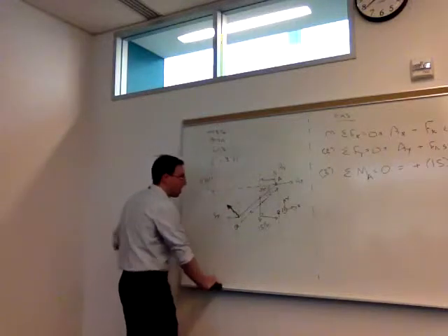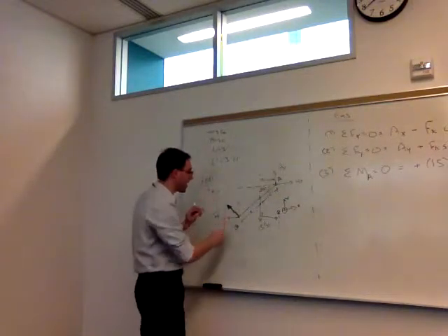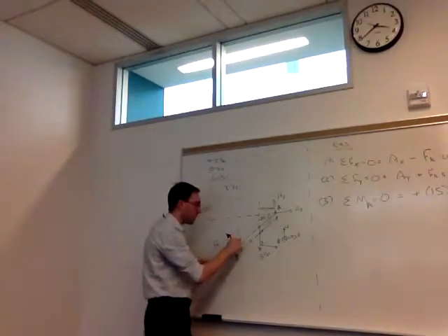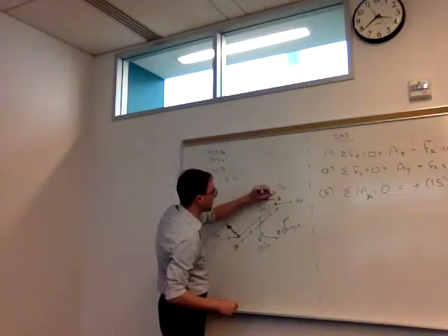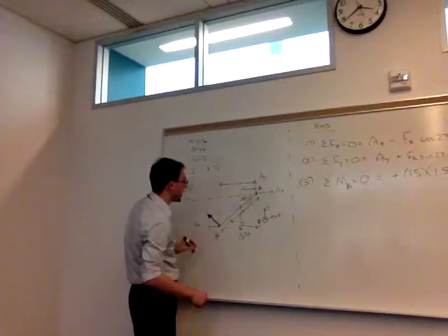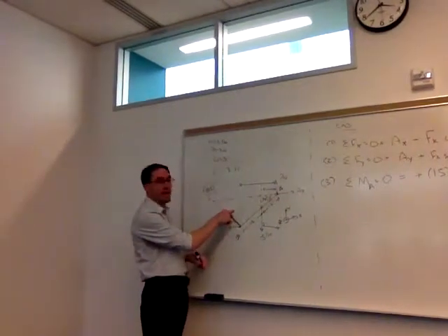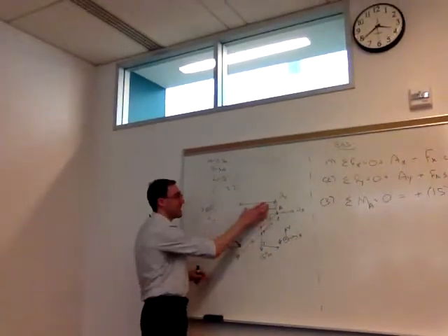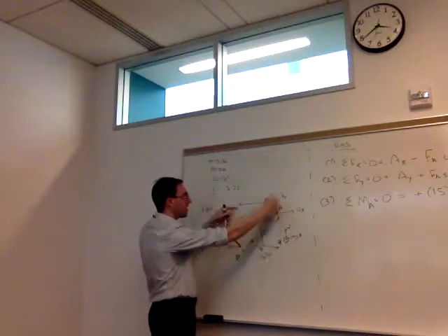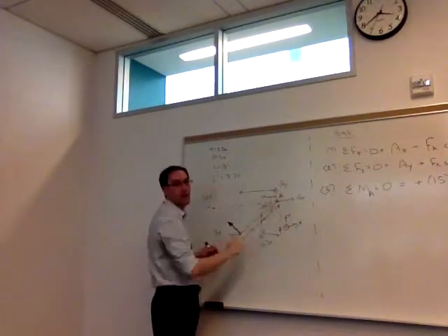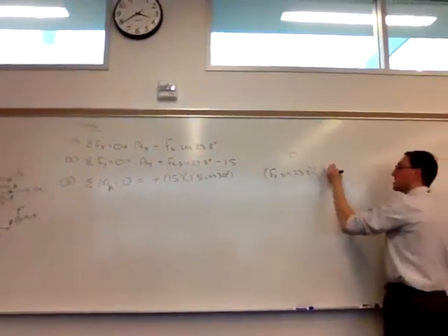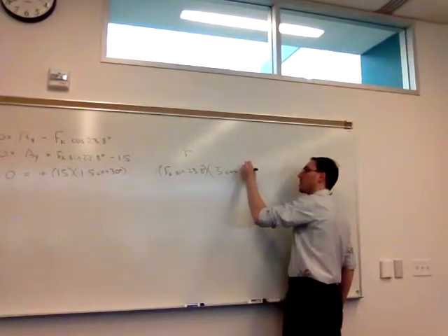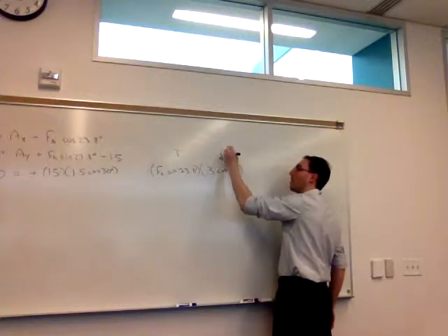And the horizontal component. So by starting with the Fk sine 23.8 degrees, that is this piece of it. So its line of action goes here. So right, this is the distance to there. So the force is Fk sine 23.8. The distance is this 3. The adjacent to that is 3 cosine 30. So Fk sine 23.8 times a distance of 3 cosine 30. Again, that's that D parallel.